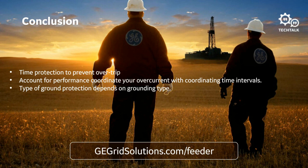And you can click yes, and then you can browse to wherever that file is on your laptop using the tool. And when you do that, it's going to build the 845 as close as it can. Now, it's going to know what firmware version you're using in the 745 because that's a portion of the settings file, and so it'll instantiate from that.